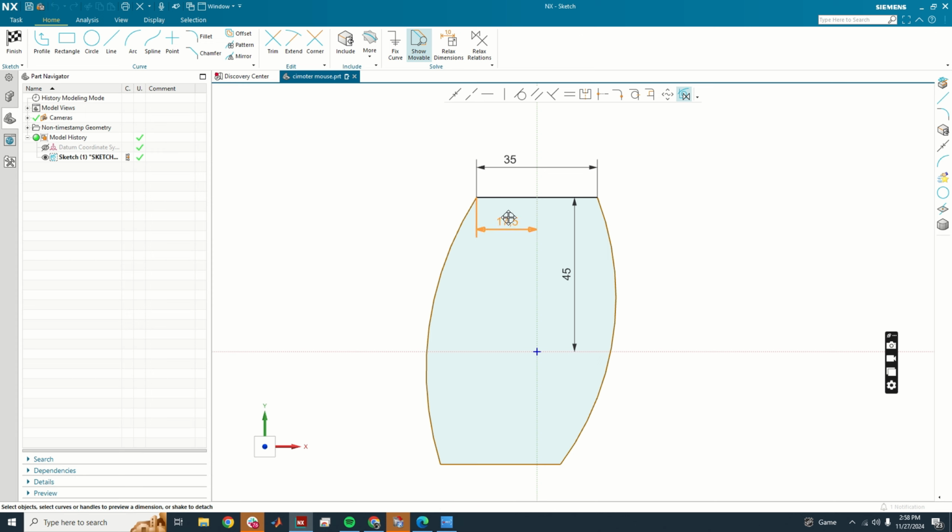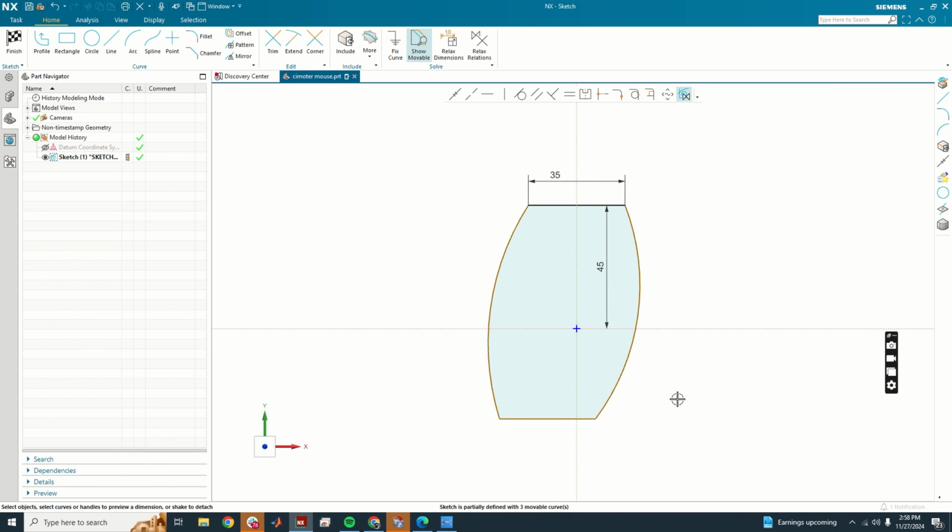If all else fails, you could always delete this line and redo it. But if you have any other sketch later on down in your item tree that references this line, and you delete that line, that reference is going to be broken, and it's going to cause some issues. So just be aware of how you're making changes when you delete things. But that's not to say never delete anything, obviously. Sometimes you need to. But anyway, I'm just going to move on from this because I don't know why it's doing that. Anyway, we just got to move on.